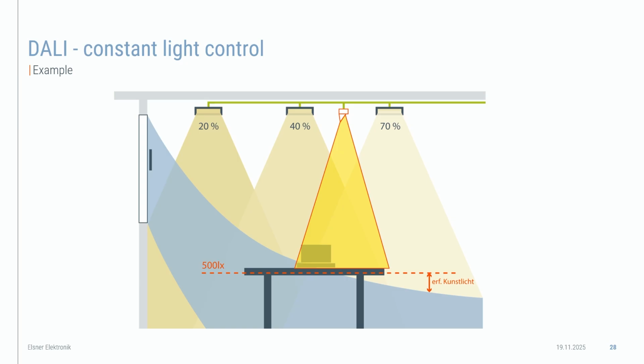And you can see on the top the 3 lights. The areas show different dimmed values, and the values can differ depending on the light. For example, you can use a threshold, and with the threshold you can switch up a light group on the window side if you have less light from outside. And all that can be automated with the constant light controller. So that's how a constant light regulation works.